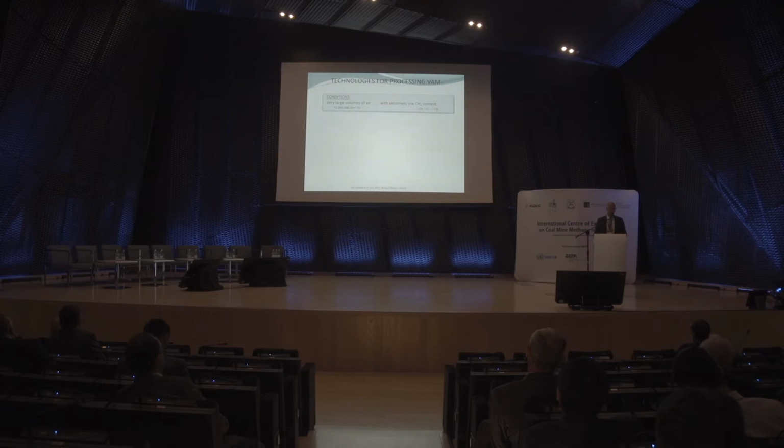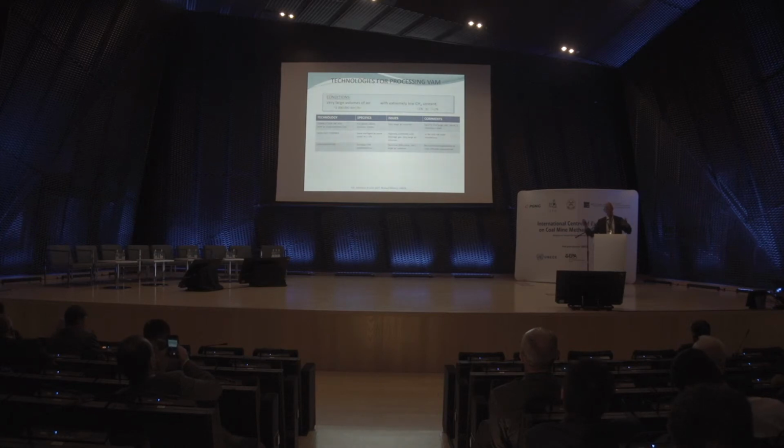We're talking large volumes, like 1 million cubic meters per year. We're talking extremely low CO2 content. So, technologies having been tried, the best way is if you have a power plant close to a ventilation shaft, then you can use the ventilation air as combustion air, and you will get the extra benefit of the energy in the 1% or 0.5% methane. But it's very rare to find such installations close to a ventilation shaft. So if you do find that, congratulations, that's a very good option.